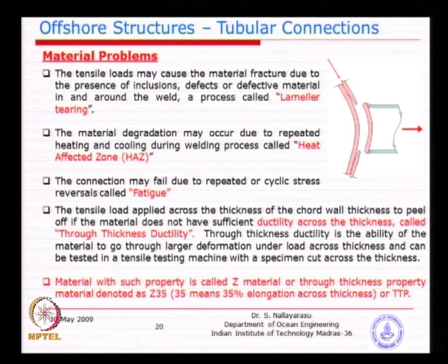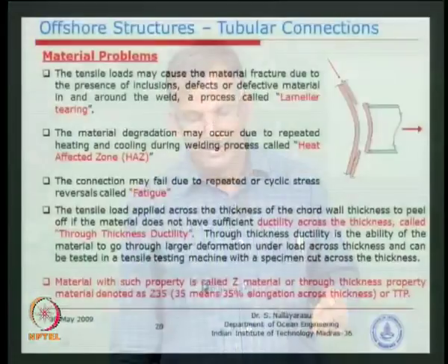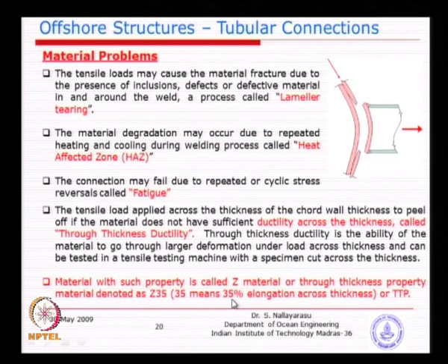example, I took only a 10 mm thick plate. It should become 135%, or basically 13.5 mm, elongated. Then it has got 35% elongation before the neck forms and it fails, because you keep on pulling, then there will be a neck formation and it just breaks. So, that means the higher the percentage the better, because if it fails at 5% deformation, it is not very good.